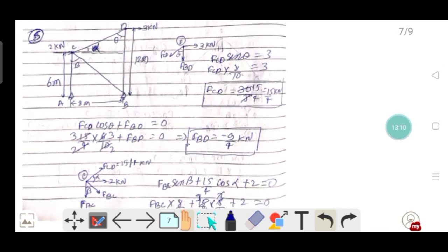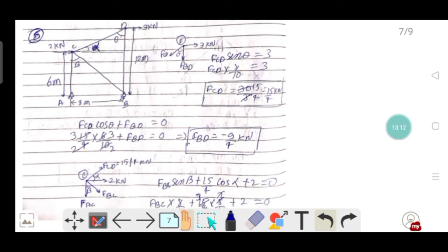Now in this way we solve all the questions of structural analysis assignment 3. The same procedure is for all the questions. First you have to calculate the reaction forces, and then the member forces by equating the equilibrium equation at each joint, due to external load and then due to unit load, and then you have to use the formula summation of N N1 L upon AE.